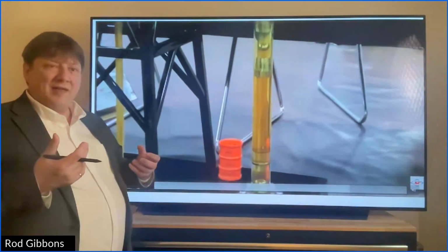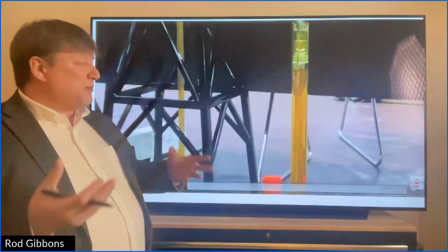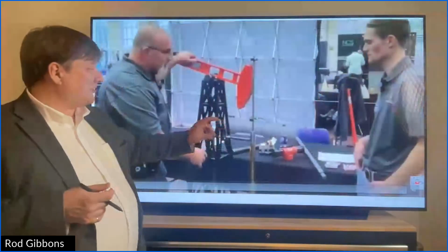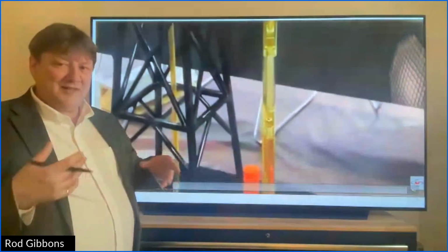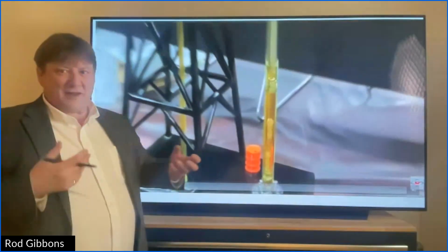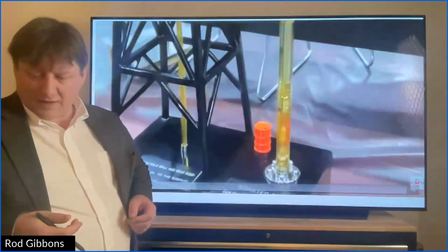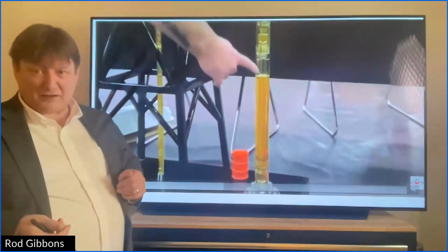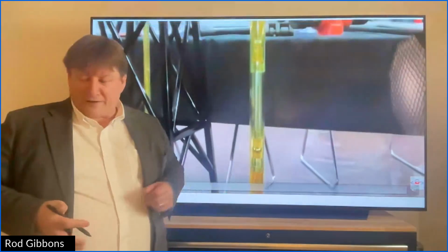Again, in artificial lift, you want to keep the moving parts moving smoothly and not having shock or changes from gas to liquid. So that's always good to keep it slow and controlled, but sometimes you don't know that until you get a failure or you collect more data. So, but again, very simple pumping system. It's just 2 check valves is all that you're using. That's what all of these pump jacks are actually. That's how they're getting oil out of the ground.